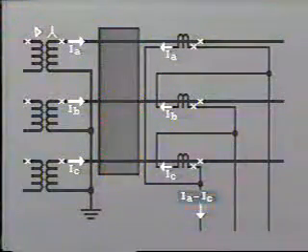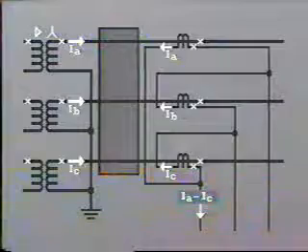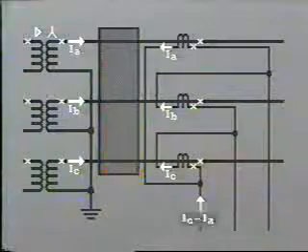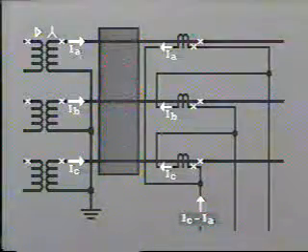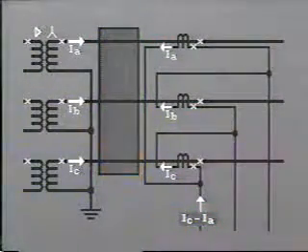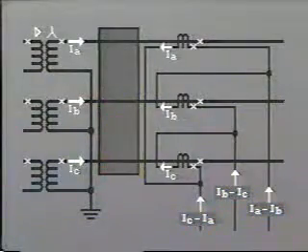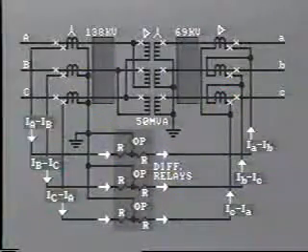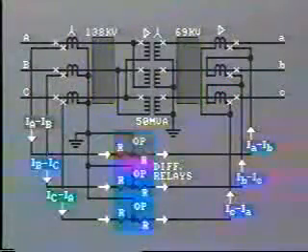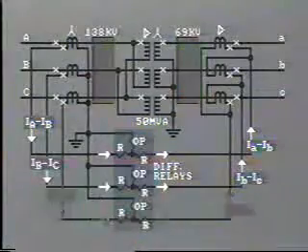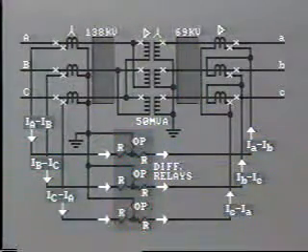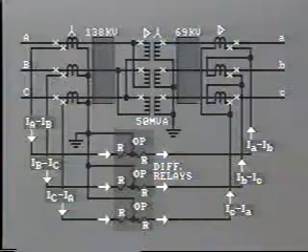But in order to compare the currents on either side of the differential relay, we must know the value of the current in the opposite direction. So this will be IC minus IA. Similarly, with the other two phases here, we have IB minus IC, and here, IA minus IB. In each case, the current on either side of the differential relay corresponds to its respective line currents. Thus, the phasing is correct.